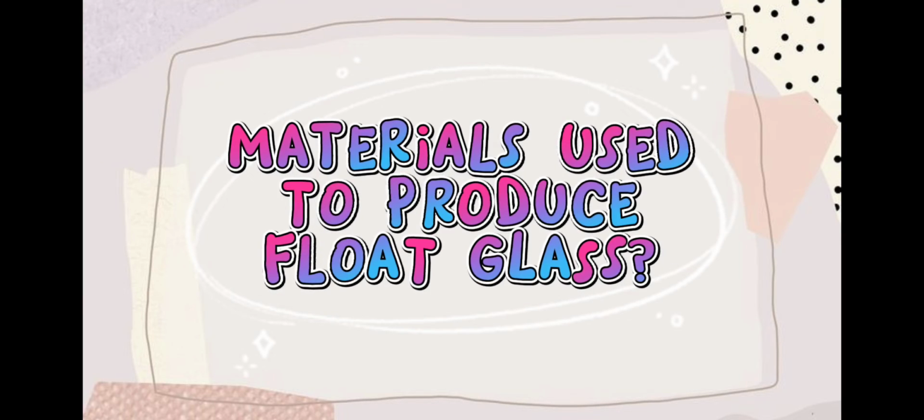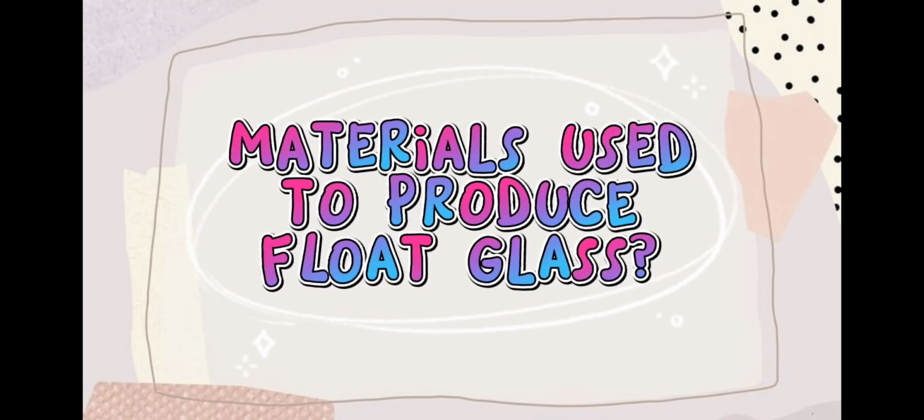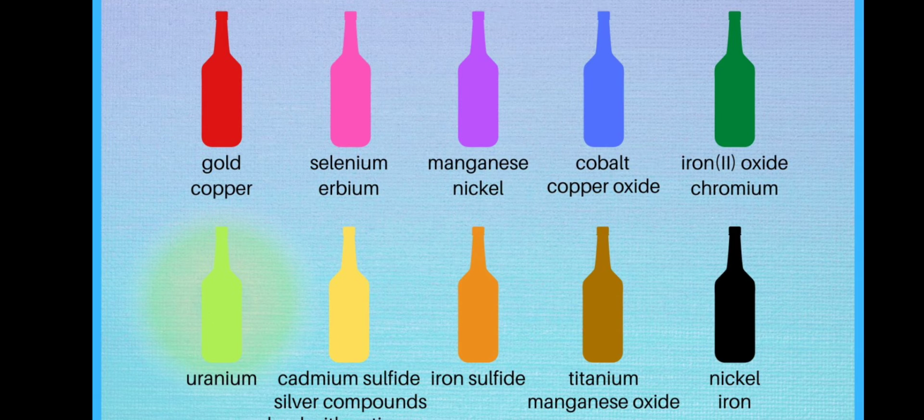Do you know what materials are used to make float glass? To produce high quality float glass, we require high quality sand, soda ash, limestone, salt cake, and dolomite, melted at white heat to a highly viscous consistency. Other materials such as colorants and refining agents are also used to adjust the physical and chemical properties of the glass. This is the basic composition of float glass, one of the greatest of all industrial process inventions, comparable with Bessemer's innovations in steel manufacturing.